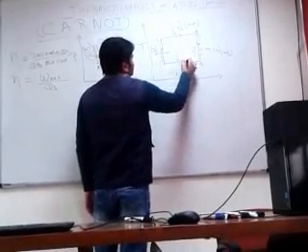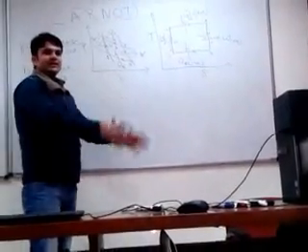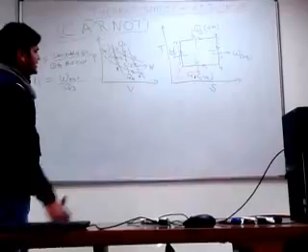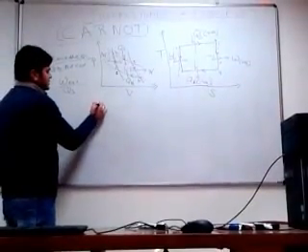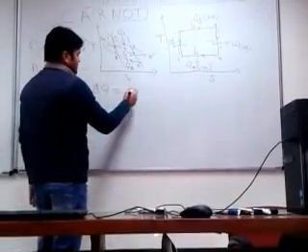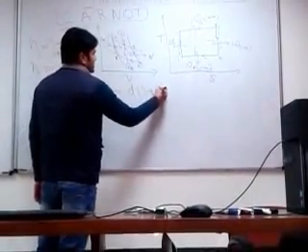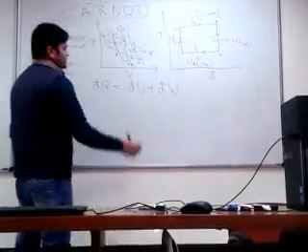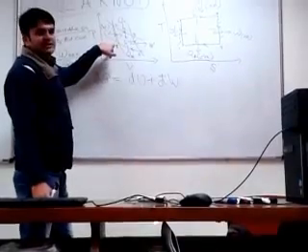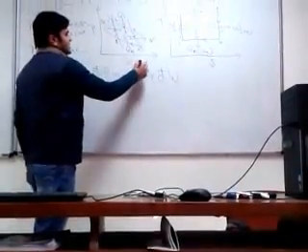So as we see that it is a clockwise cycle, so it is a work producing cycle. And for a cycle, due to the first law of thermodynamics, we write the first law: the heat transfer equals the change in internal property plus work done. For a cycle, the change in property is zero because the initial and the final state of the cycle are the same.